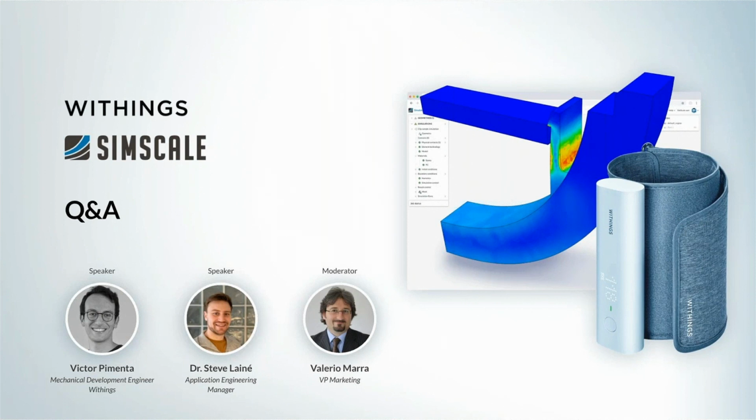Also, there is a good point about SimScale, which is that we can really check the solve log live. We can really see if the residuals are high. We can see whether the overlap is happening between these two parts. So it was somewhat easy to define it with the iterative process of simulating this part. As Steve has well said, we can really iterate over the penalty coefficient as well as over the design. It's a really interactive process with the integration between Onshape and SimScale. It was very helpful to have this connection between the two platforms.